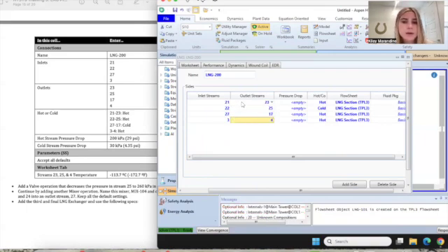For this combo, it's going to be hot. 22, 25 is also going to be hot. 27, 17 should be cold. 3 and 4 should be hot. For hot streams, pressure drop 200 kPa and cold 30 kPa.